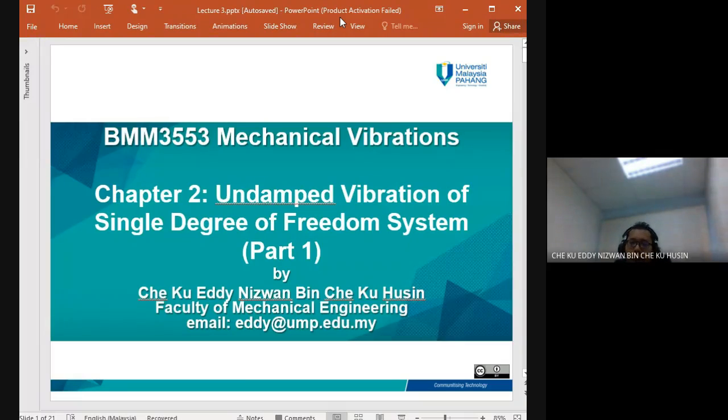For this subject, basically for the first half of the semester, we look at a single degree of freedom. You can divide it into two chapters: chapter 2 for the undamped system and chapter 3 for the damped vibration system. Today we cover part 1, where we are looking at free vibration. Free vibration means that the system vibrates on its own when you give the initial conditions, without any external force. So basically it's a self oscillation.